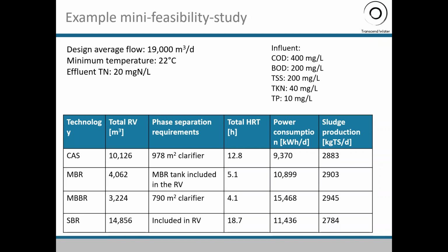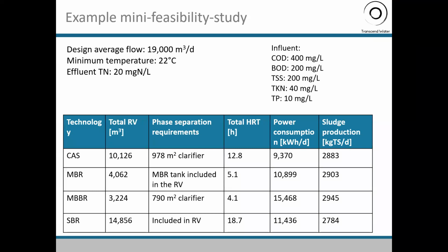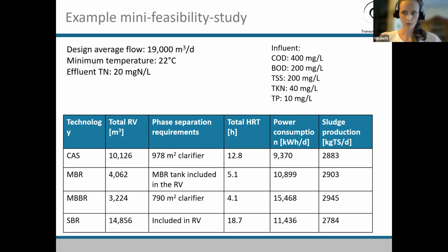Yes. And then John also had a follow-up on the sludge blanket level detector. So the answer that we provided, he said, not exactly, since if the plant receives a high F/M or high load influent, you need the sludge detector to react to the higher biomass. One indicator is higher MLSS, but you may need to increase the RAS. These kind of details are not incorporated now into this preliminary design. This is a preliminary design, what this system is doing. So we are not accounting for any extra stuff like this. We are always calculating with just the given concentrations, given loads, and not taking into account these extra things, only the return from the sludge.